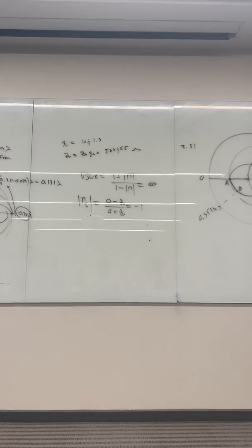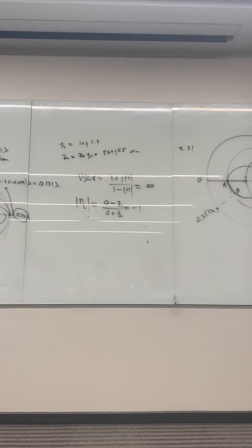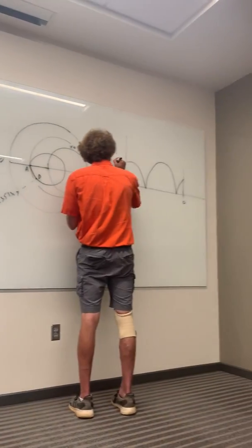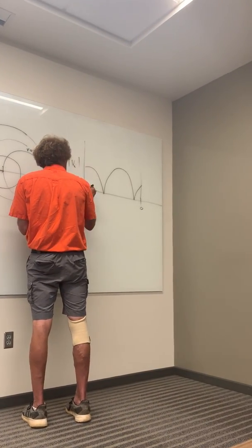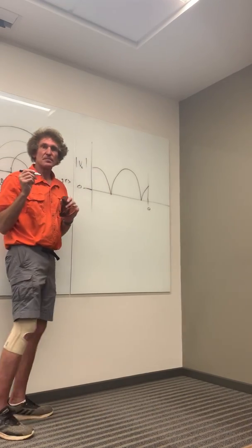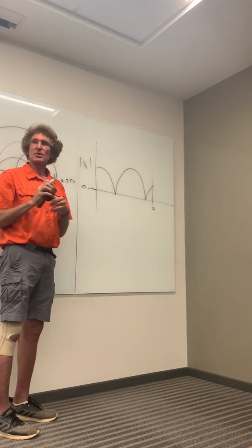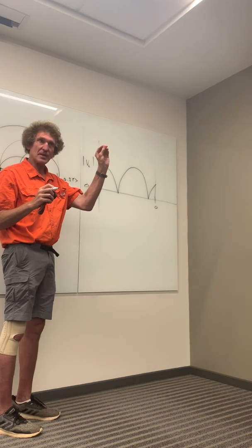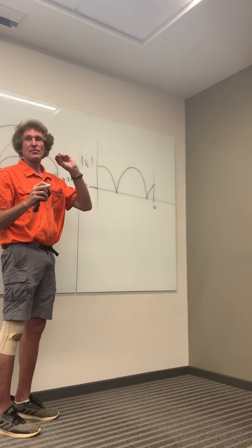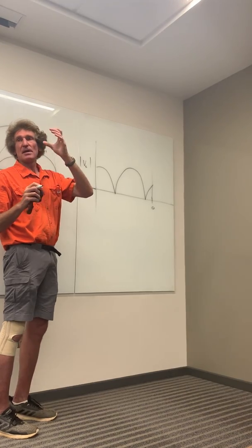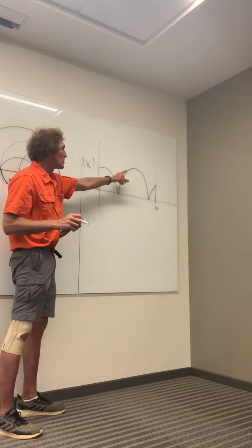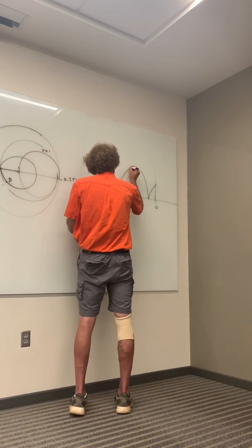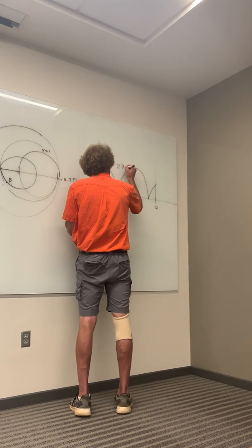Oh, he's just showing you the voltage. The actual VSWR will be infinite, because take a look at this. This is the magnitude of the voltage on the line. You see how this is the 0 point here, class? Now, when you have a short circuit, what happens on the line is the voltage magnitude's peak will double the actual input voltage. If you input a generator voltage of say 5 volts, your peak here will be 10. Are you with me? So whatever the voltage is you put in, you'll get 2 times the magnitude of V